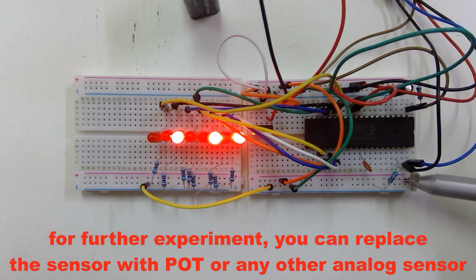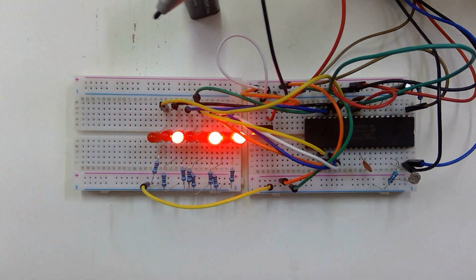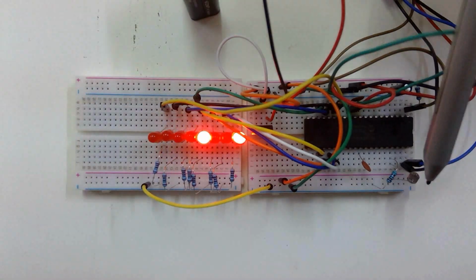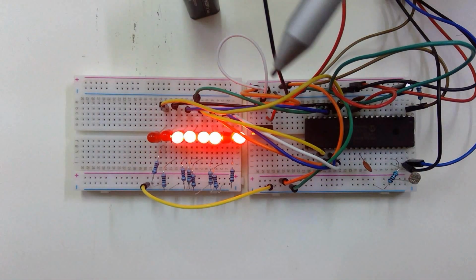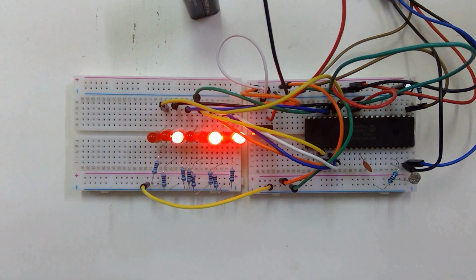experiment. You can replace this light sensor with a potentiometer, and you can set some voltage divider. You can configure the potentiometer as a voltage divider and measure the voltage and display it on the LEDs. In place of that, you can connect any other analog sensor and you can measure its result on the LEDs. So follow the schematic diagram and download the program using MPLAB snap and complete your activity.